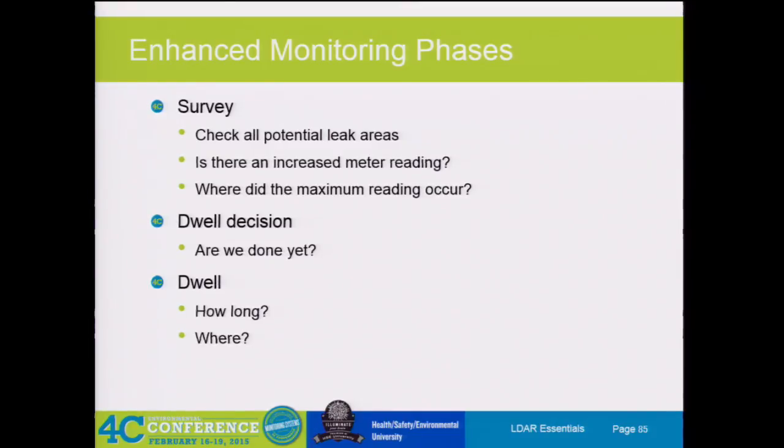It helps, but if your technicians are torquing it and they over torque it, now they're just going to create a bigger leak. They also don't understand that when we go in to do a repair attempt, they should step away for a couple seconds, because as you tighten that, you're actually pushing the gas or whatever might be in there back out into the atmosphere. So you're going to get a higher reading. If you step away, let it settle back down, and then redo it, you're going to be able to fix it. Just a thought.